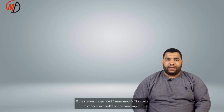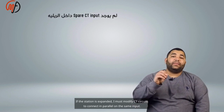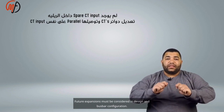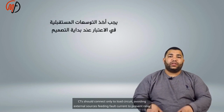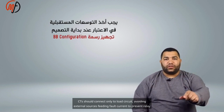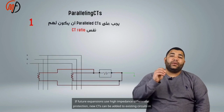If the station is expanded, I must modify CT circuits to connect in parallel on the same input. Future expansions must be considered in design and busbar configuration. CTs in parallel must have the same ratio. CTs should connect only to the load circuit, avoiding external sources feeding fault current, to prevent relay errors. Ensure the total load current from the CTs does not exceed the relay CT input or winding rating.